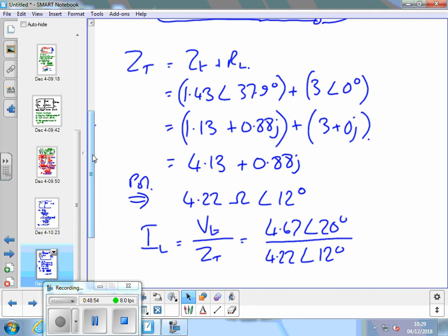So, yes, it becomes a bit more long-winded mathematically and uses up a lot of paper, but Thevenin's with an AC circuit and superposition still uses the same process. Still requires this understanding of replacing sources with their ideal impedance. Okay?